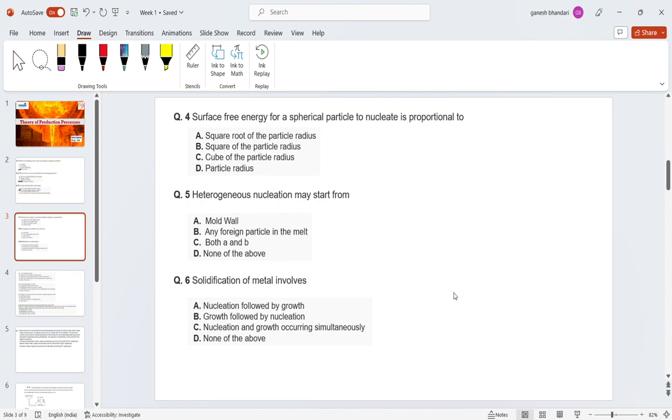One example I will give you again is for tin, because I am presently working on tin, so that's why these are coming to my mind. If you talk about tin and copper, suppose whenever a tin droplet is poured onto copper, tin starts diffusing into copper, because they form intermetallics on their surface. They form different intermetallics like Cu3Sn and Cu6Sn5.